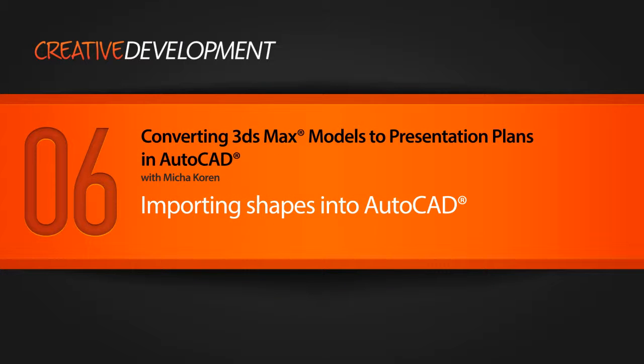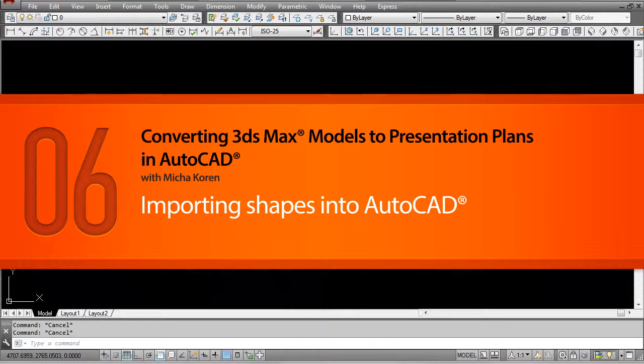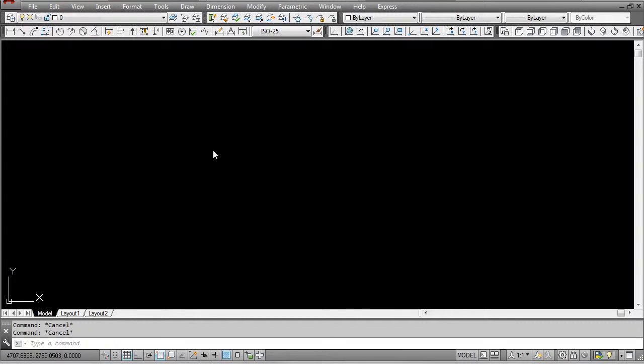In this lesson, we'll learn how to insert, edit, and flatten the plans extracted from 3D Max in the last lesson. Now, the first thing I'd like to show you before you bring anything in is that there is sometimes a difference between units in your two different programs. For example, in AutoCAD, I like to use millimeters because things are much more detailed, and in 3D Max, I use meters because I'm working on the building and things are a lot larger. So make sure that you have that set up correctly.